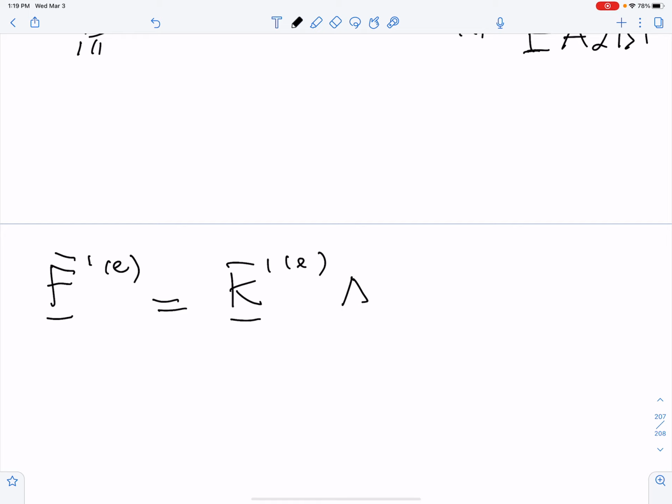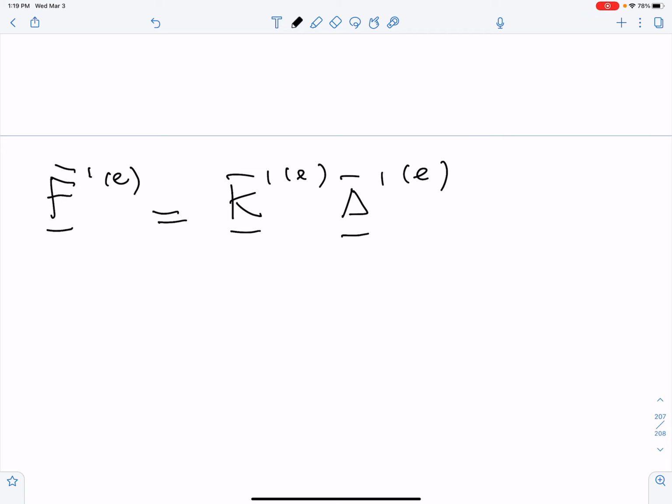So then in that case, how do we model loads? We say, for a given element in the basic coordinate system, because now basic forces make sense, we're going to decompose the force into K prime for that element times delta prime over bar, which would be the forces that are coming from the displacements.